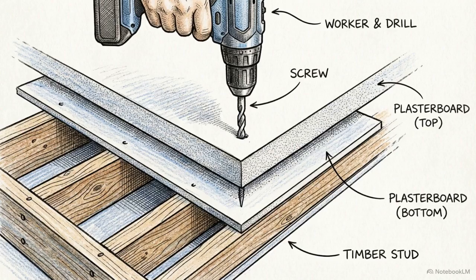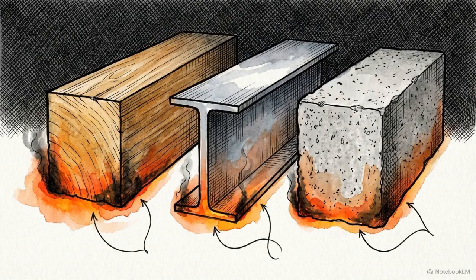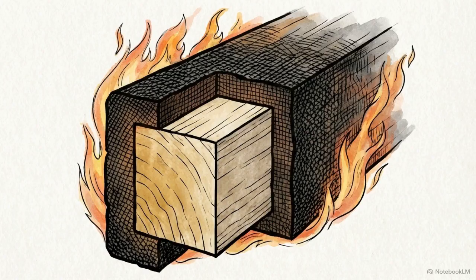On active sites, temporary compartmentation can be quickly achieved by cladding a studded timber frame with 2 layers of skimmed 12.5 mm plasterboard. Once a fire starts, different construction materials fail under severe thermal loads at vastly different but highly predictable rates. Dense timber actually has high fire resistance.